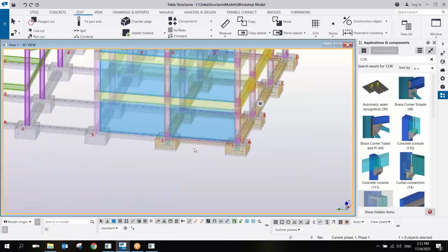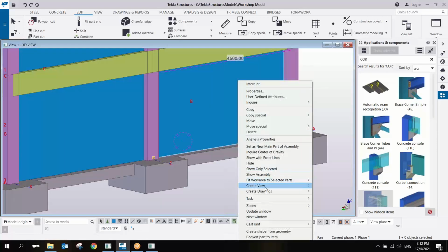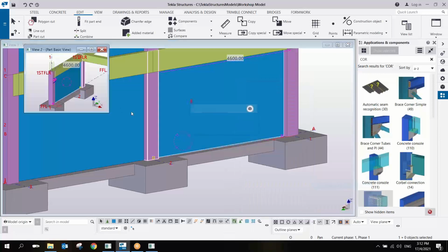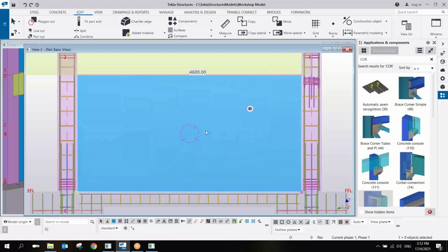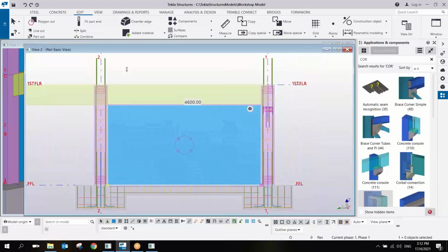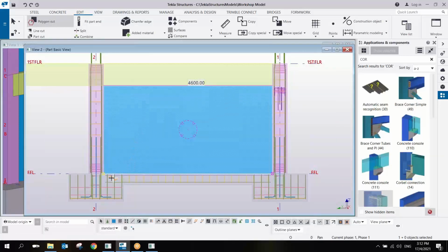Even in the wall, let me just simply isolate this wall, create 3D view, okay, this 3D view means I isolated this wall. So here, if I have the opening in this wall, let's say I have the door opening, so select the wall, and then here pick one, then 2 meter, 900.